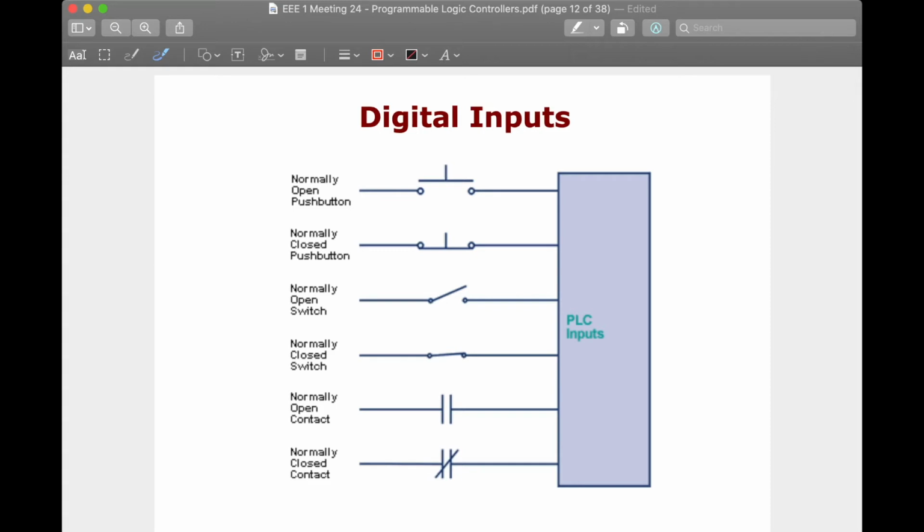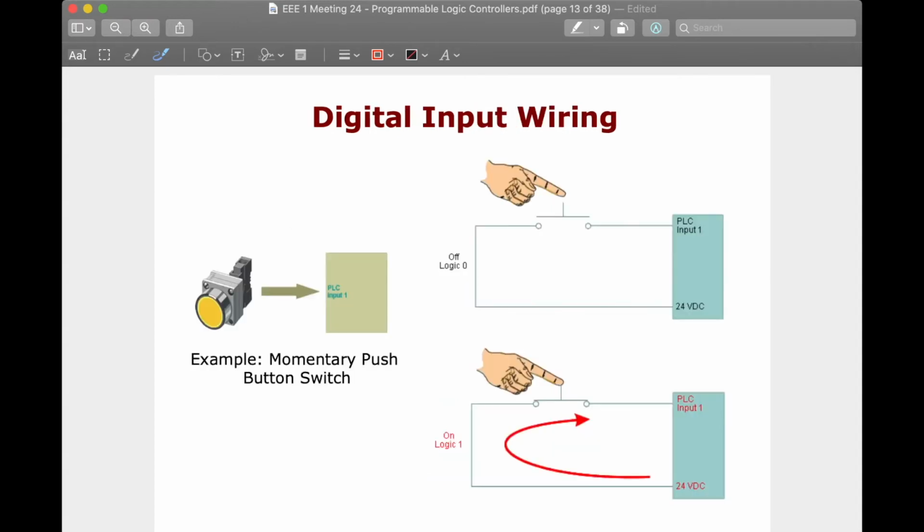So you also have the relay or contacts. With the relay, instead of a manual operation acting on it, it is usually an electrical signal. When there's an electrical signal that energizes your relay, for example, a normally open relay, by default it's going to be open if it's unenergized. When it's energized, it becomes short. And when that energizing source continues to exist, then it remains short. And when it is unenergized, it becomes open again. So yeah, I just explained that here earlier.